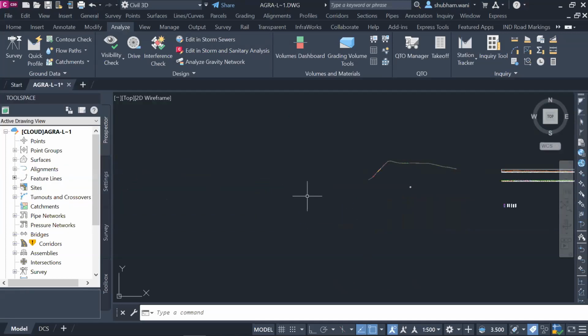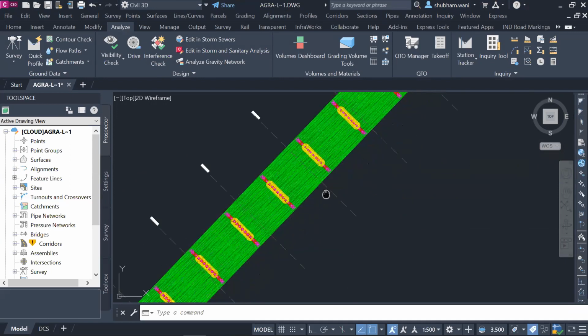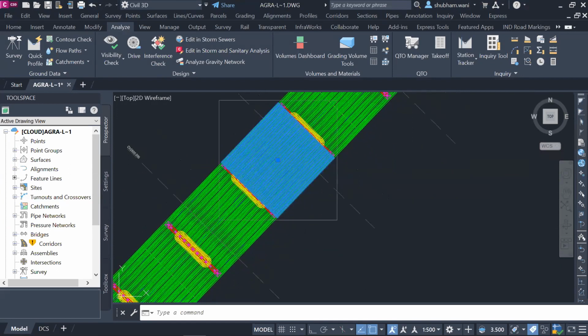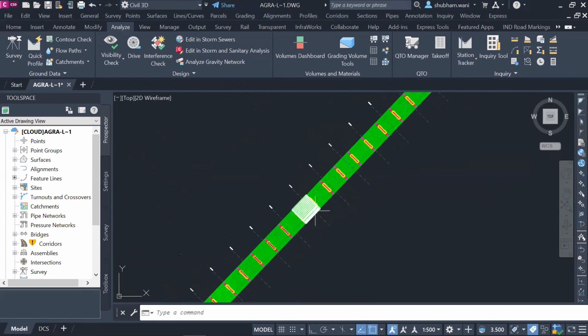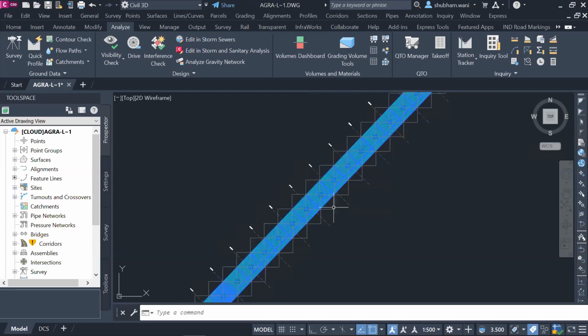So I'll be assigning to the material. So I'll be simply going into the bridge section. So some of the people from structure as well. So I'll be selecting the bridge area from slab culvert, slab section. Whenever we're selecting a slab, the bridge slab deck. So here it is the option as a point code as ETW. So when assigning to the pay item, then it will be reflected into the material I will be assigning.